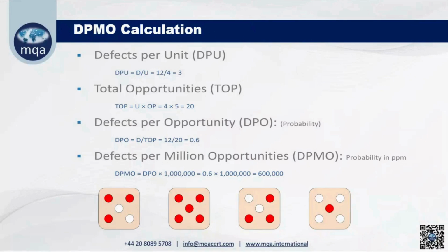Now in manufacturing, thousands of parts are manufactured, so we cannot calculate it this way, with 600 or 700. So what do we do? We use a term called defects per million opportunities, DPMO. People use billion opportunities also. It depends on the highest unit you can go to, because at production level we are producing 1,000, 5,000, 10,000 or even lakhs of units per month. So it is very important to have a higher figure, so we go for DPMO.